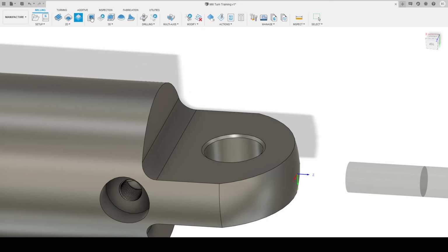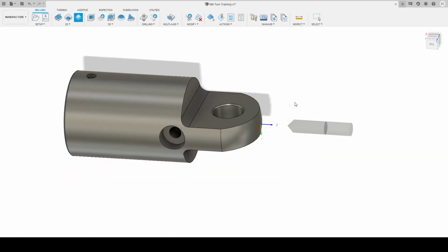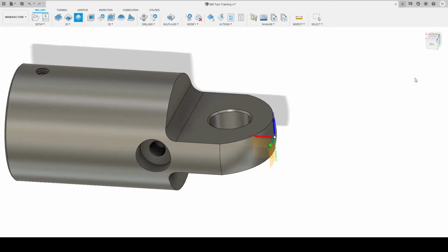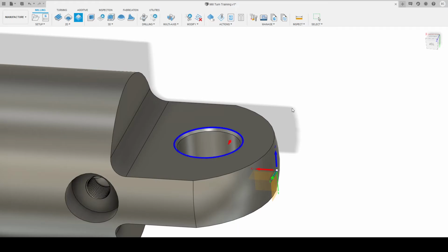Cutting data, we'll leave that alone. Post processor, we'll give it a unique number, which is 5. Accept that, select that. We'll orientate our tool because it's not in the right orientation. So again, under geometry, under tool orientation, we'll select the Z axis. And then under contour selection, it's asking us what do we want to chamfer. So we will select the top of this geometry.